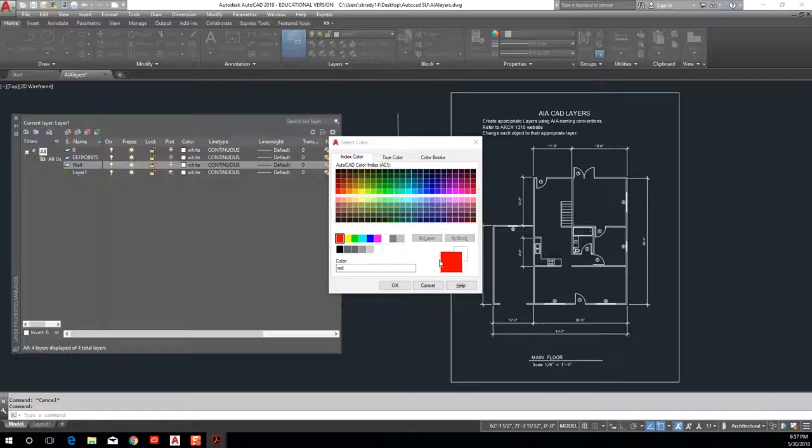Now, I'm going to show you in the book how you can go about assigning colors to your layers, right? But I also want to say that if you're thinking about layers, and I see that thought in your assignments, I'm okay with that. So you may say, hey, red is the thickest pen weight, but we all get sort of finicky when we start doing AutoCAD and drawing. Red is too heavy, right? And people have really adamant stances on this, which is even funnier. But red is too heavy. We don't like to use red for our heaviest pen weights, okay? That's great. Use yellow, right? Yellow can be your heaviest pen weight.